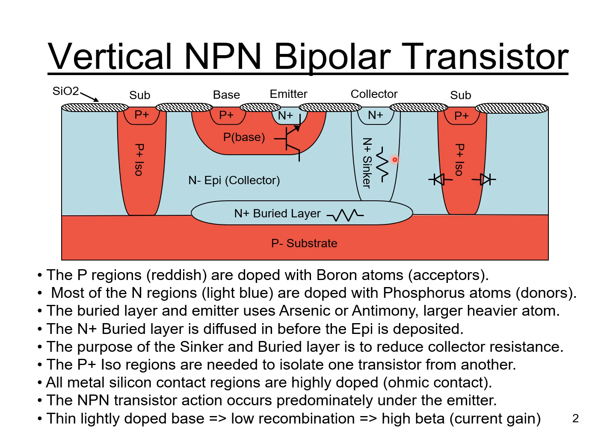However, there are two exceptions to the phosphorus doping. That's the buried layer, which is the blue region at the lower middle of the drawing, and the N+ emitter at the upper region of the drawing. Both of these regions often use arsenic or antimony to dope emitters and buried layers.